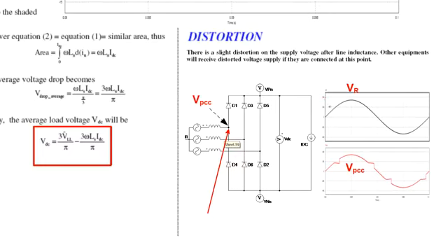This is the voltage from that point to the neutral point. Similar to the red phase voltage, here we have the voltage just before the source inductance, which is from the source. We have a nice sinusoidal voltage, but due to the rectifier, the voltage at the point of common coupling has been distorted.